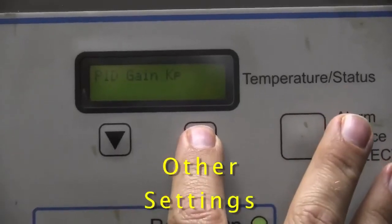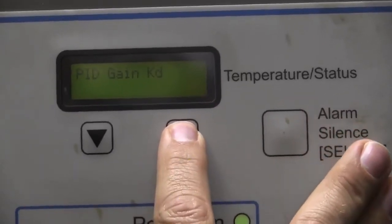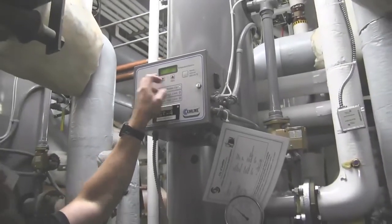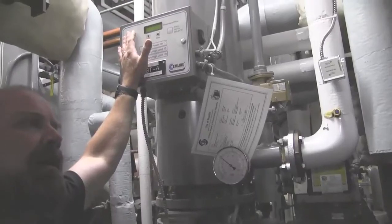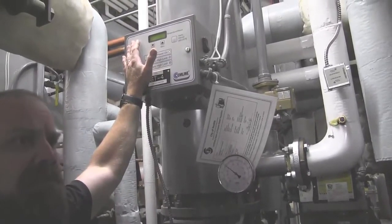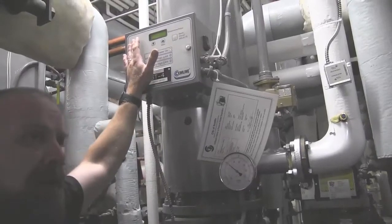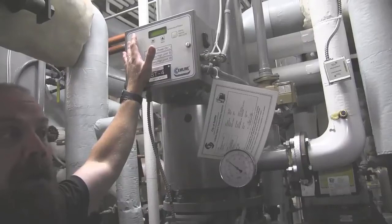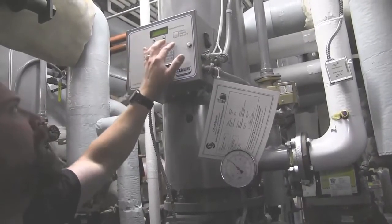59415. Your PID, your proportional gain throughout, I wouldn't make changes to that unless you were on the phone with tech support from Cemline. We can walk you through it if you're having issues with the system overshooting or undershooting, and Mike over at our office would be the one to tell you what settings to put that at and go from there.